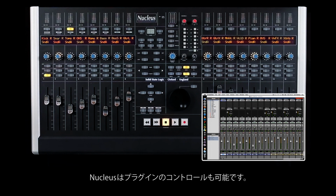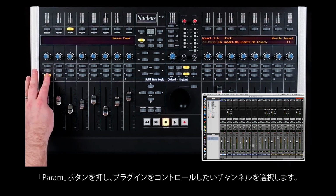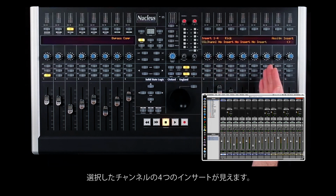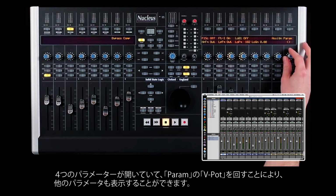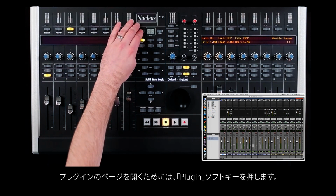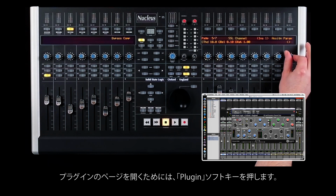You can also control plugins using Nucleus. To do this, press the Param button and then select the channel on which you wish to control the plugin. You will see the first 4 insert slots of the channel you've selected. Simply press the V-pot to open up the parameters. If your plugin has more than 4 parameters, simply turn the Param V-pot to access the other parameters. And to see the plugin on screen, use the Plugin soft key and see the parameters scroll between them.